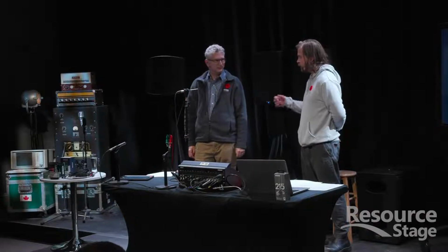And you mentioned as well, it's logarithmic. That's right. The amount of change in the level from 0 to 10 on this mixer is going to be quite a bit more than from -20 to -10. See those two numbers there? That's going to make a slight change in your level. That's going to make a massive change in your level. So as you go up, the change is logarithmic. Does that help? Excellent.